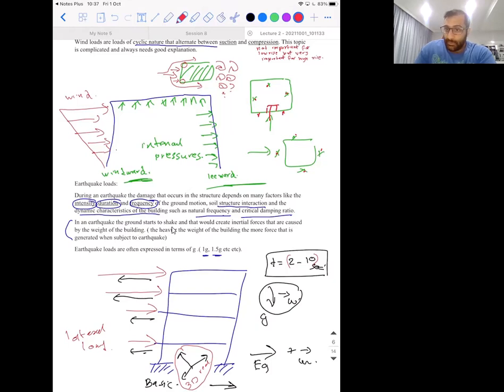And that's a problem with earthquakes, because usually they would tell you to increase the section when you're failing a criteria. Like if you're failing an earthquake criteria, increasing the section is not an option. Because when you increase the section, you have more load now, more inertial forces. So more earthquake load, which basically means that you're going to collapse easier.